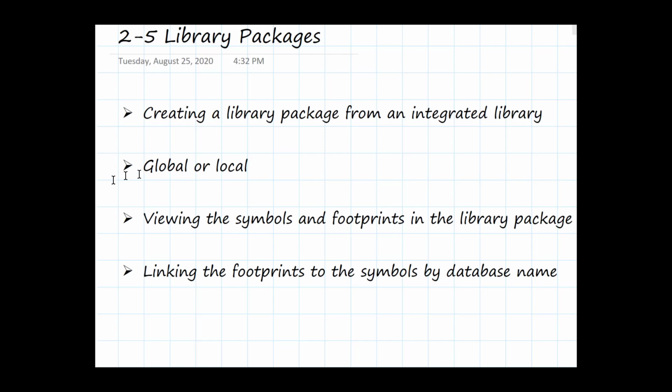We're going to look first at using a library package as a global library. In a later video, we'll talk about how we can use local library packages. And once we open up that integrated library and we turn it into a library package, we'll be able to view the symbols and footprints in the library package. And I'll show you how we link a footprint to a symbol by the database name.